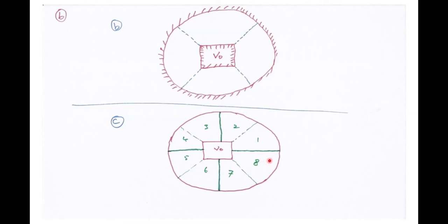Now the rest of the work is easy. Just fill one of the big flux tubes with sub-flux tubes and curvilinear squares. Then you can easily determine the capacitance of this structure.